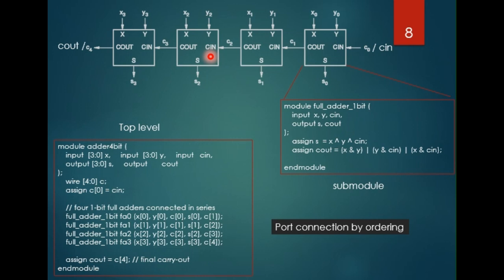Okay, let's look at how to expand a single-bit full adder into a 4-bit adder. This block shows the module of the 1-bit adder we designed earlier. Note the inputs X, Y, and carry in as shown in this diagram, and the outputs are sum and carry out. So we expand the circuit: the full adder, we instantiate it 4 times.